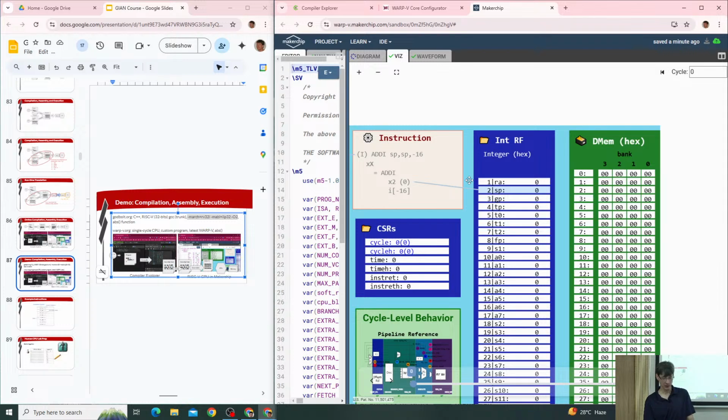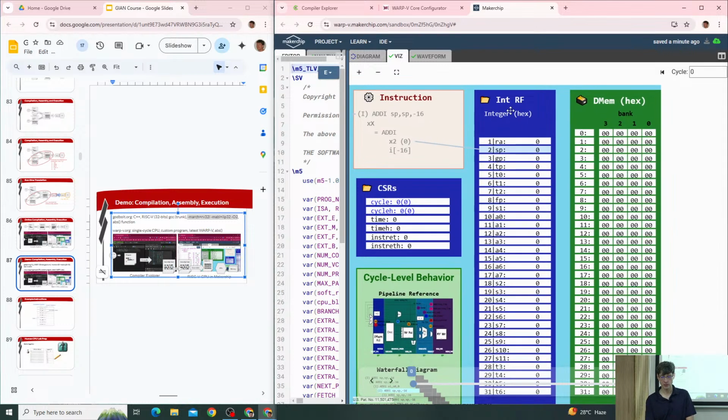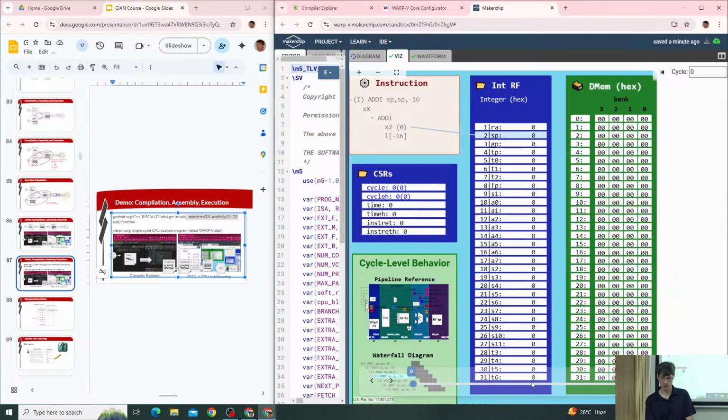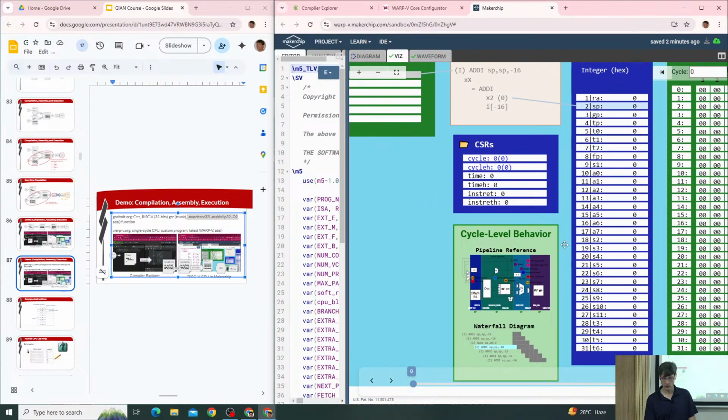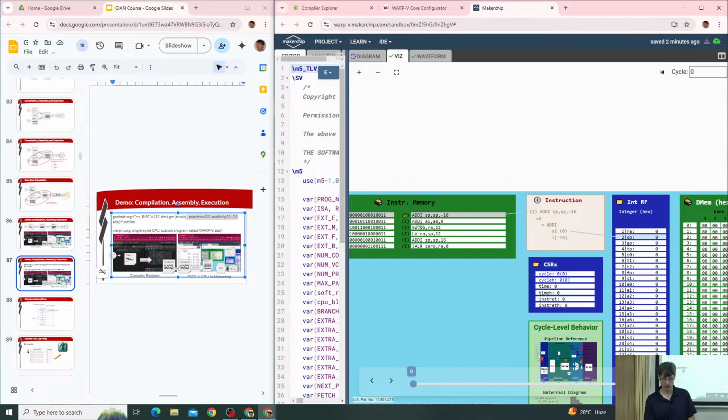So again, trying to remember what we talked about. Okay, so RISC-V is what's called a load store architecture, which means the majority of the instructions are operating on values from the register file. So we have a register file with 32, actually 31 values that instructions can read and write. And we have memory. The instruction set architecture has specific instructions to access values to and from memory, so loads and stores. We also have a more detailed view here.